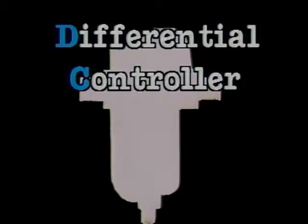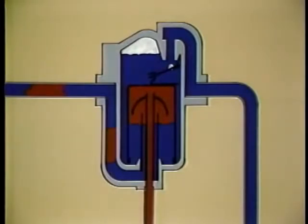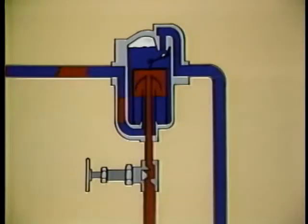The automatic differential condensate controller is a unique drainage device that is able to vent large amounts of flash steam and non-condensables. It may also be used wherever a live steam purge is needed to scrub the system. The DC operates under the same principles as the inverted bucket steam trap and is constructed similarly. The important difference is a secondary discharge tube which runs from the center of an umbrella-shaped shield coaxially through the inlet tube and is metered by a manual valve at its outlet.